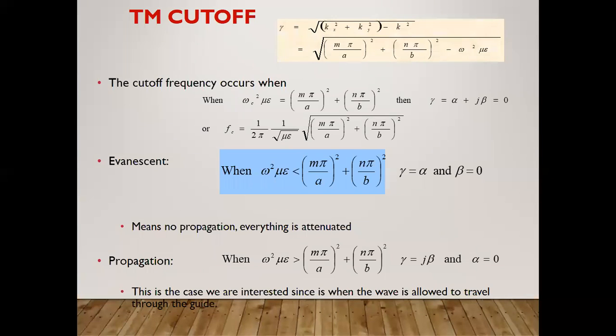Totally depending upon the case, we can calculate easily. If I am talking about the transmission line, the things will be different; if I am talking about optical waveguides, that will be different. So similarly here you can observe the change easily. The propagation constant gamma is equal to alpha plus j beta. Instead of that, here we are writing this propagation constant for the TM mode. So we can write it in the form of x as well as y by looking at that coordinate.